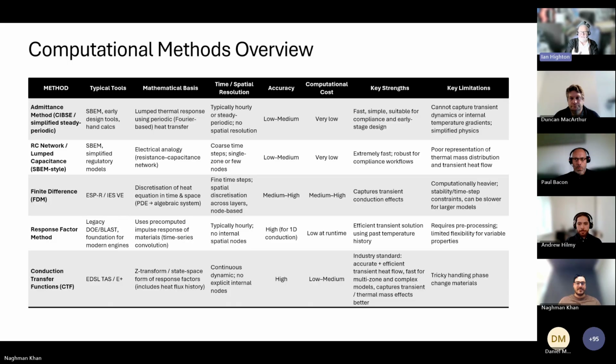The one thing I don't understand about EnergyPlus, because it uses the same conduction transfer function ideas, the Z transform stuff, state space stuff, is why it's so slow, but I think that's because they've coupled the building to the HVAC modeling side of things. So it's almost like the HVAC modeling slows stuff down, whereas we've stuck very much to: you do the building simulation, you get your room weighting factors, and then you go and do your HVAC simulation. People either love that or hate that, but it's much quicker.